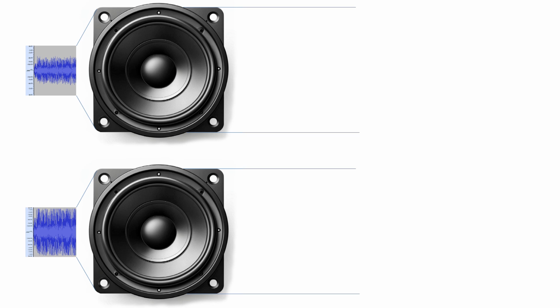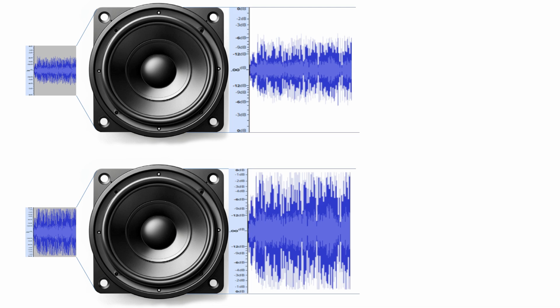Take a look at these audio samples. One is below reference and the other goes up to the reference point. What is the reference, you might ask? And why is it not optimal that one is not reaching the maximum level? You can imagine the reference as the maximum output whatever system will be later used for playback. If a listener has a small radio, then it might be, for example, 20 watt. If a listener has a big system, then it might be 100 watt. Whatever system it is, if you define your audio to reach only half the possible reference point, then the system will never be able to reach the full intended loudness.